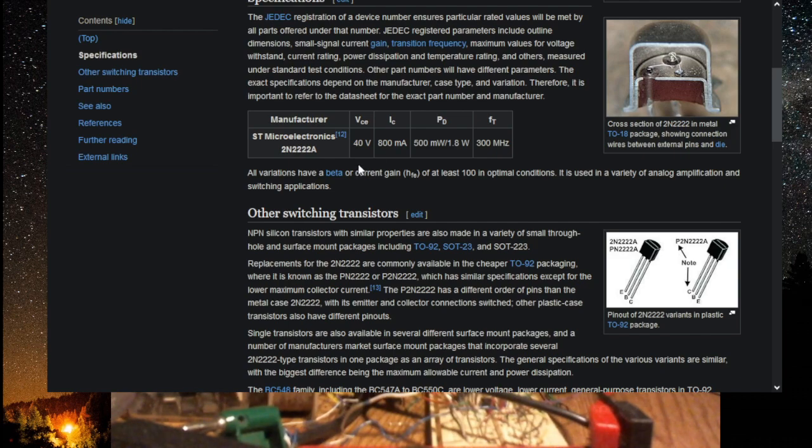It's a high voltage collector emitter, which kind of bothers me a little bit because 500 milliwatt, I mean, this is cranking. It goes up to 300 megahertz. Maybe that's okay because what we want is circuits that have high transient response, and I'll talk about that in a minute. But what I want to look for is the other one, 2N3819.